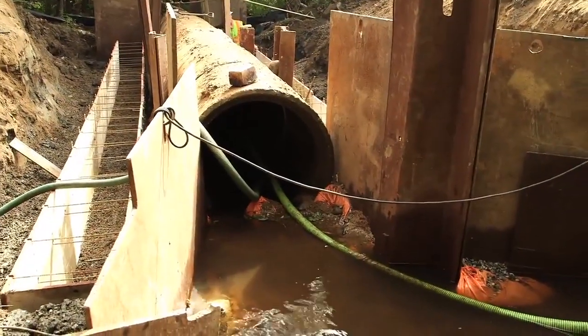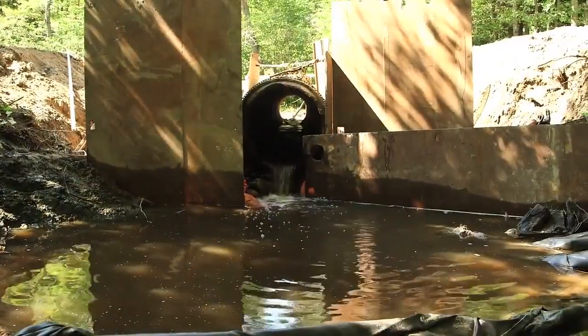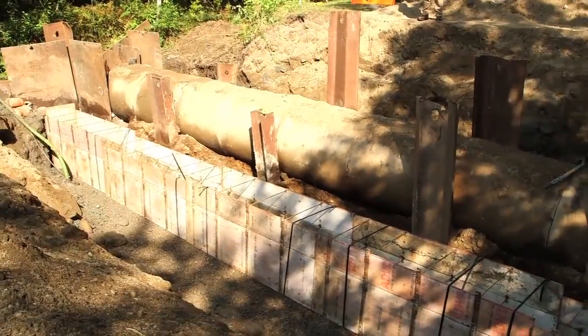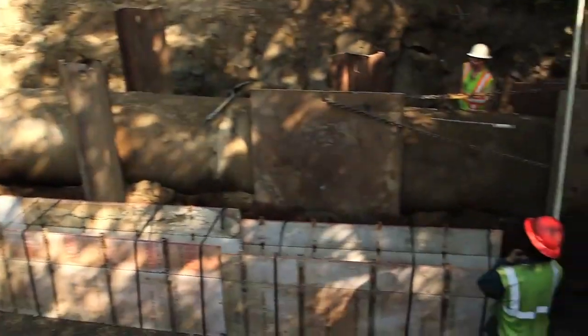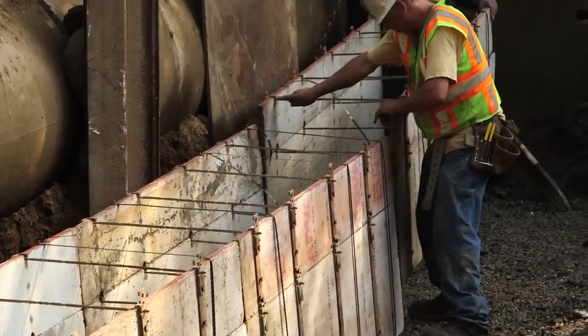The pipe was left in place during the construction of the concrete footings. Leaving the pipe in place allowed the flow to go through the working area and kept the flow away from where the footing construction was taking place. Utilizing the existing pipe for the stream to bypass through the site also eliminated the need to pump any stream flow around the working area.